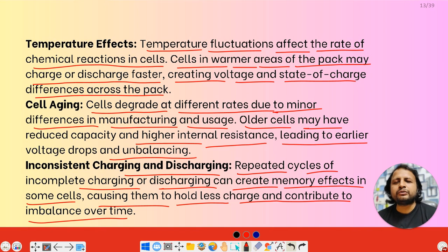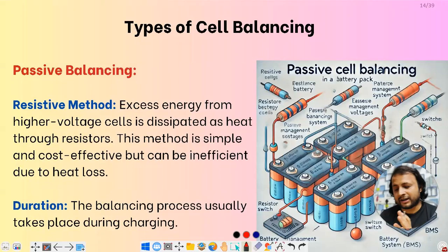So make sure when you are charging, keep it at least more than 80% or 100%, charge it. Because if you are connecting your vehicle for one time charging, so that one cycle is completed. And in one cycle, if every cell is not getting a full charge, so that means what, we are playing with the life span of the battery pack. ओके, सो आई थिंक अब तक आपका क्लियर हो गया होगा.